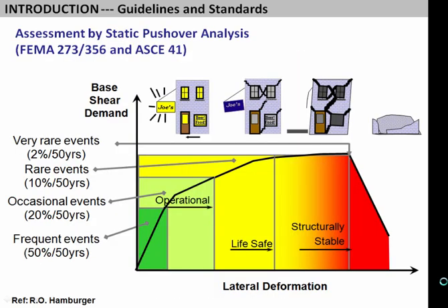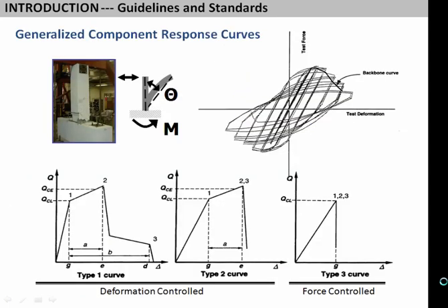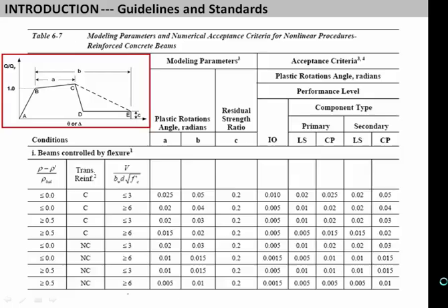But as Ron mentioned, it was really FEMA 273 introducing static pushover analysis, apart from the performance framework, that really got some of the key essence of thinking about how you do nonlinear analysis for design into practice. That distinction between the elements that are so-called deformation controlled and force controlled, and the key thing there is the ones that are deformation controlled, those are the ones we have to model nonlinearly. Those that we choose to model elastic, by definition, will be force controlled, and their acceptance criteria determined accordingly.